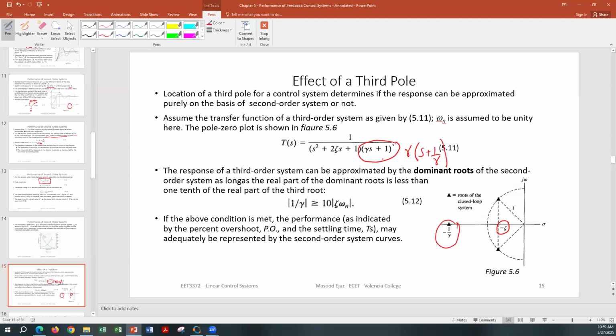As your second order. So you don't really have to rewrite it. Because the whole thing is to calculate the performance parameters, like the peak overshoot and so on, even if you don't want to rewrite it, if you use those equations that we discussed in the last slide, you can just use those equations and calculate the peak overshoot and so on. And those are going to be very close to the actual values if you plot the system, including the third order pole. But as I said, if the third order pole starts coming closer and closer, then it's going to affect all the values, and then the calculated values and observed values will be quite different from each other.